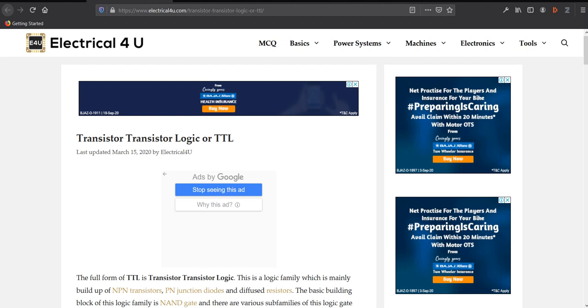Then X makes one more transition. Doesn't matter, it will continue to remain 1. When the next clock comes, it will again take the D input, which is 0, and it will go to 0 here. During this positive edge of the clock, the preset input is removed, so it will go to 0. That is how you will keep constructing the waveform.